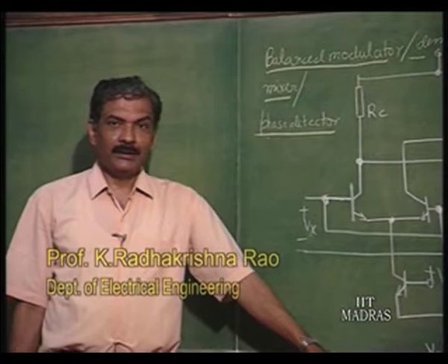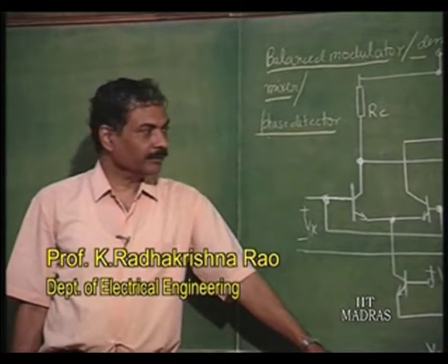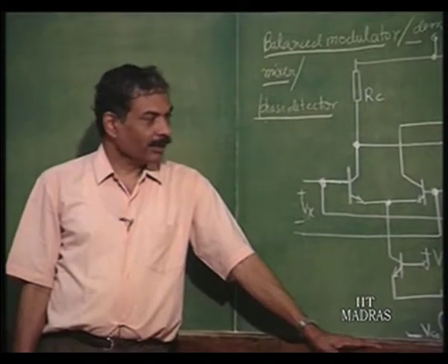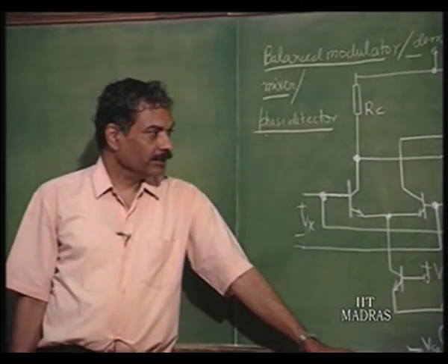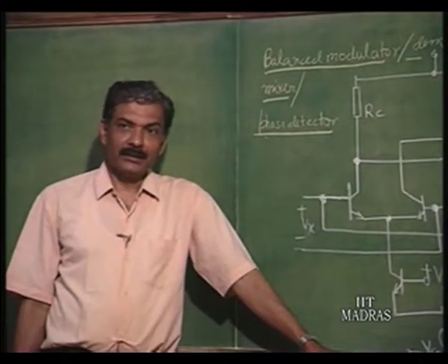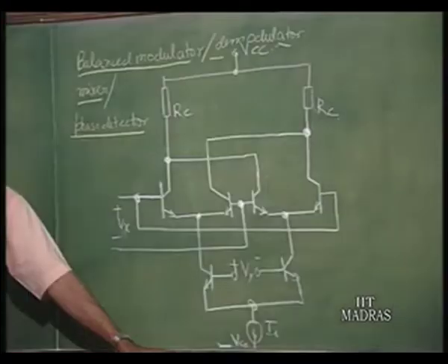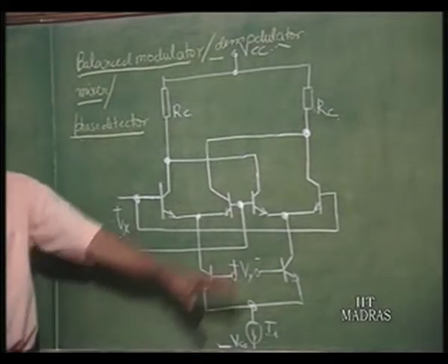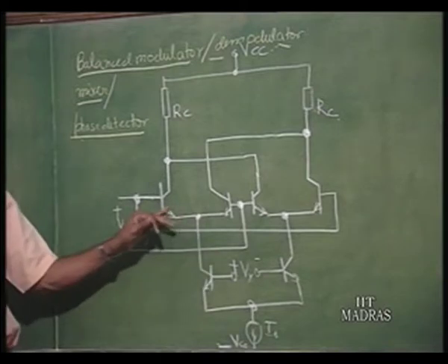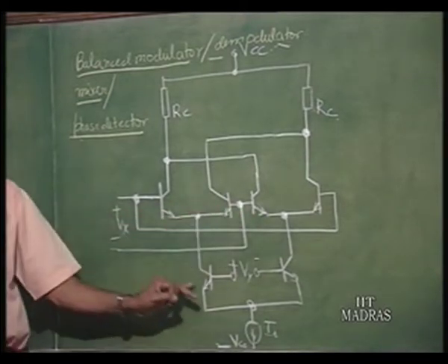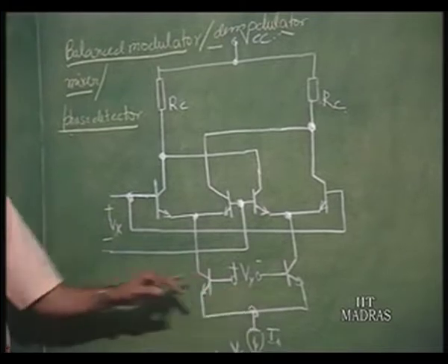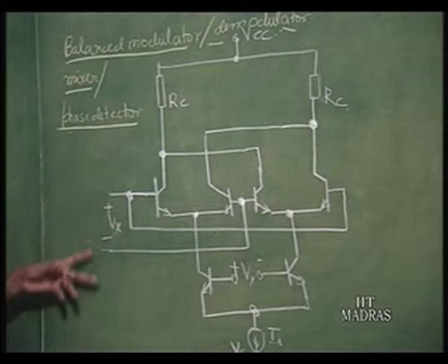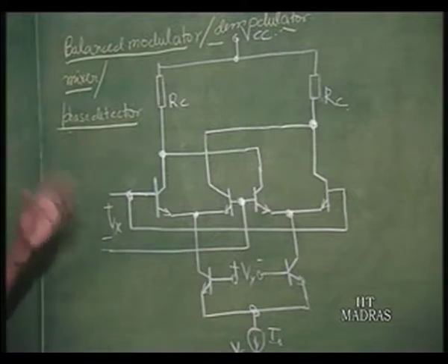We had discussed the transconductance multiplier and its applications. I would like to point out here that for the communication application of the same multiplier, there is no need to use the precision multiplier as such. You can see the basic block comprising of the pair fed by V y, and there was a transconductor converting V x into differential current feeding onto a diode that can be removed.